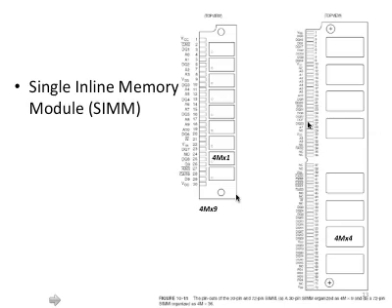That is to say, each chip has 4 million addresses, and each of them addresses 1 bit. So out of this one chip, you will have 1 data bit, and you will have many address lines. You can calculate how many.